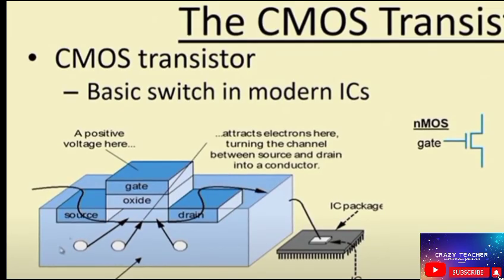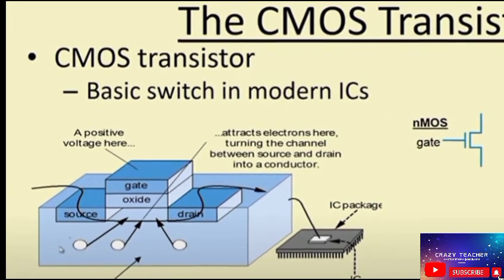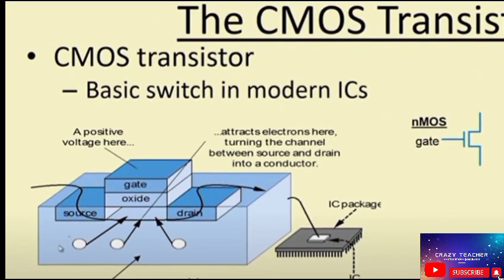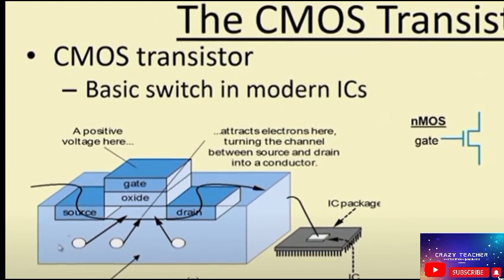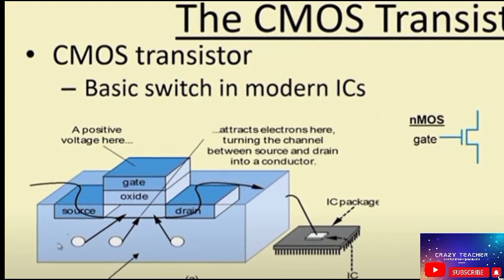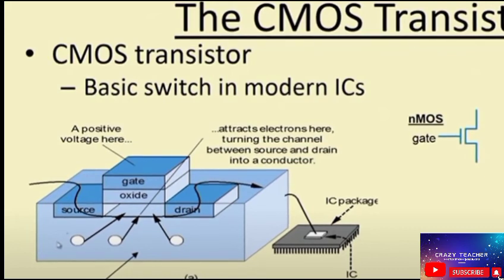On that semiconductor block we have got two dedicated regions. One is called a source, another is called a drain. They have got some type of impurity diffusion. So if this semiconductor block that we have is, say, p-type semiconductor, then on these two regions we put some n-type diffusions. One region is called source, the other region is called drain. The region in between is covered by a silicon dioxide layer, and on top of that we put another layer of polysilicon gate.